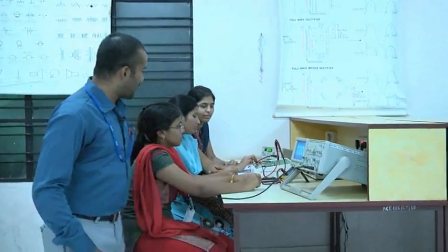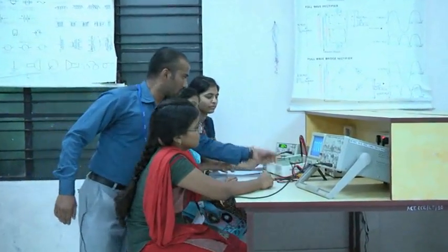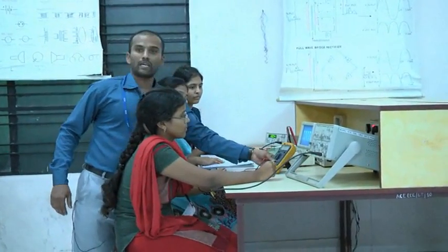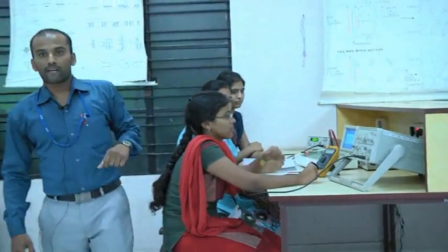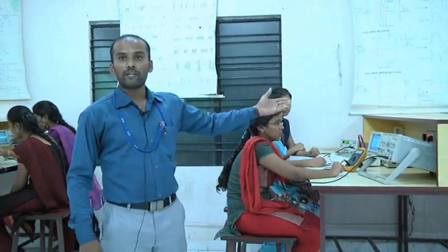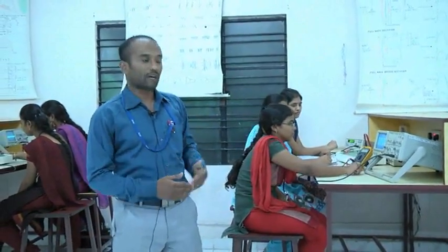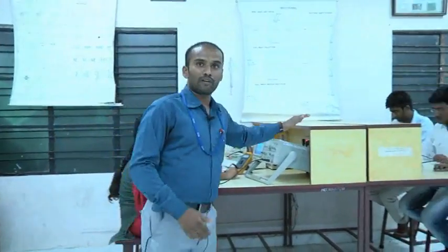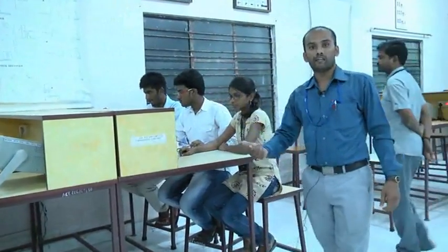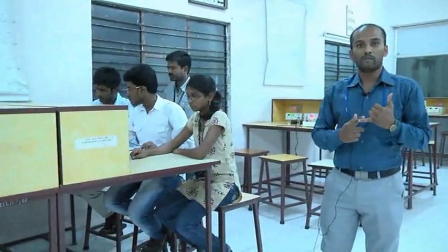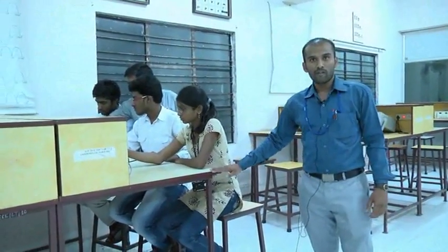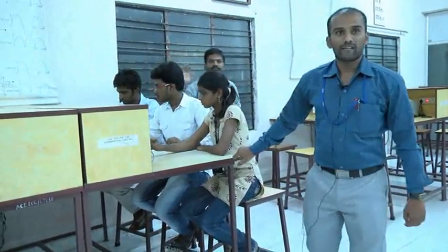By directly connecting the power supply here and the input from the function generator, we can check the output on the CRO, and by using this multimeter, ammeter, you can calculate the value of current, how much current is passing through. By using these values, we can calculate the efficiency of the class A amplifier. The circuits we are practically doing are very useful after completing your BTech, for doing mini project and main project also, and it is better for your experience of electronic circuits.